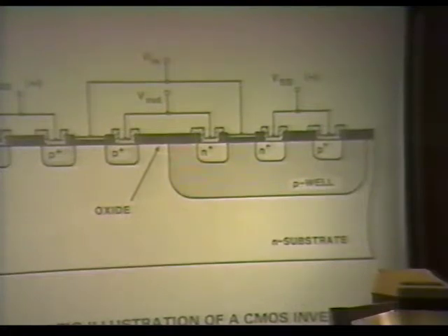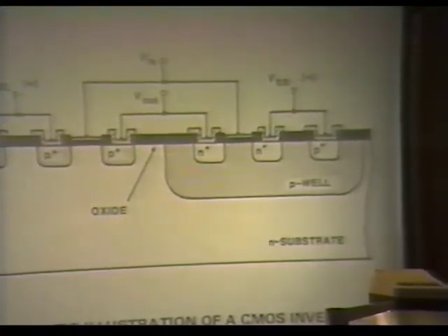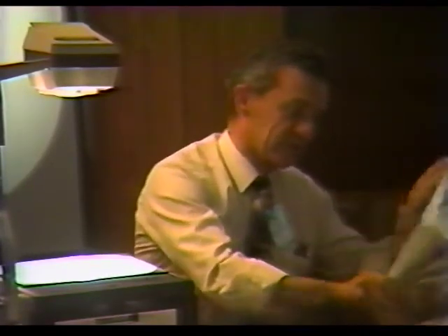What's the disadvantage? Why doesn't everything go with DI then? Tough to build. I mean, some people have trouble building EPI, and so DI is even harder. You get into real tough material problems there. So that's one of the, what should we call it, side effects that come into building CMOS that we don't want, but we can't do away with.